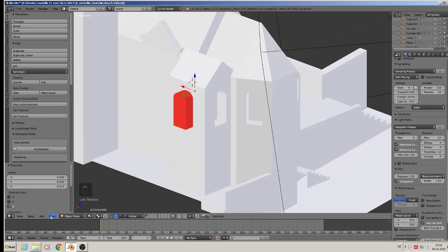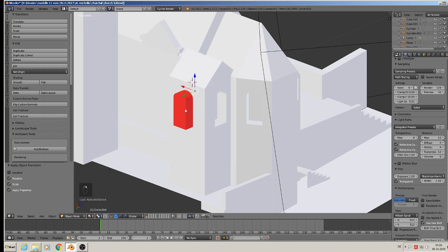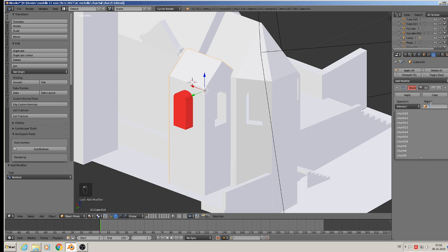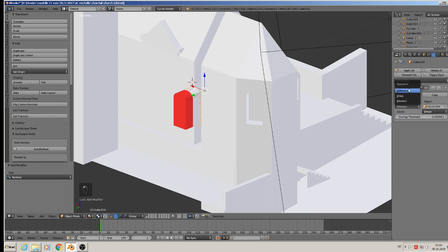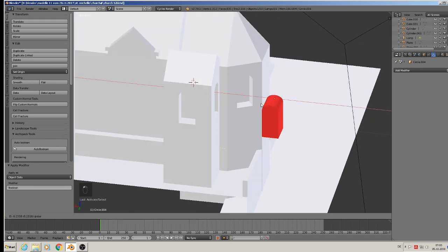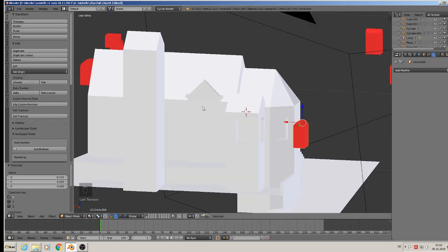Good. So Object, Apply Rotation Scale, the same with this little tower there too. Object, Apply Rotation Scale, then the name of the reddish one is Circle 4, so we go to that little house there and add a boolean, Circle 4. We take here difference and apply that. So this hole is also in. File, save. Here we can get problems maybe later, because we cut two objects that are not really one, but we will see.